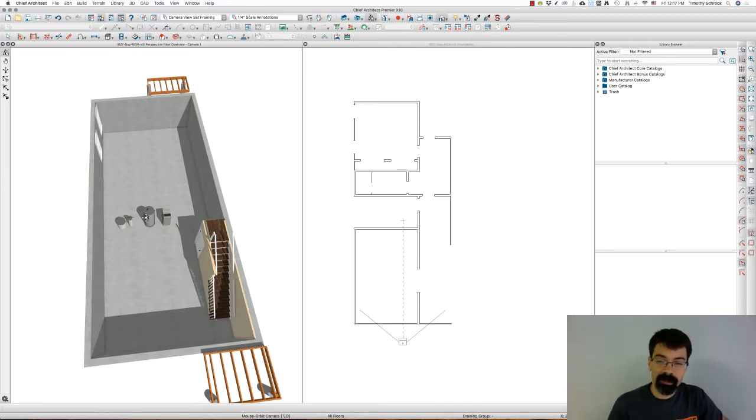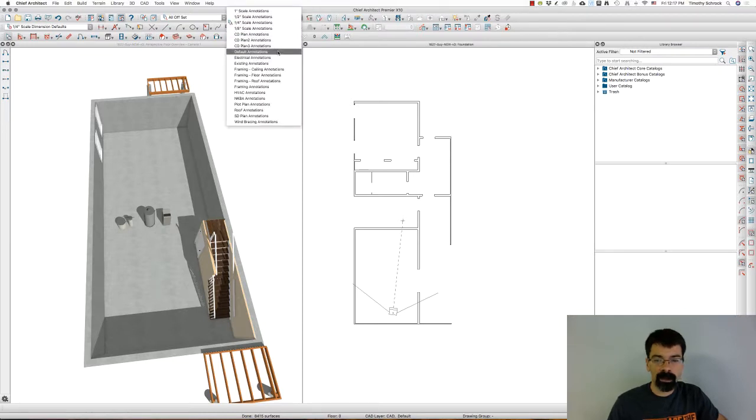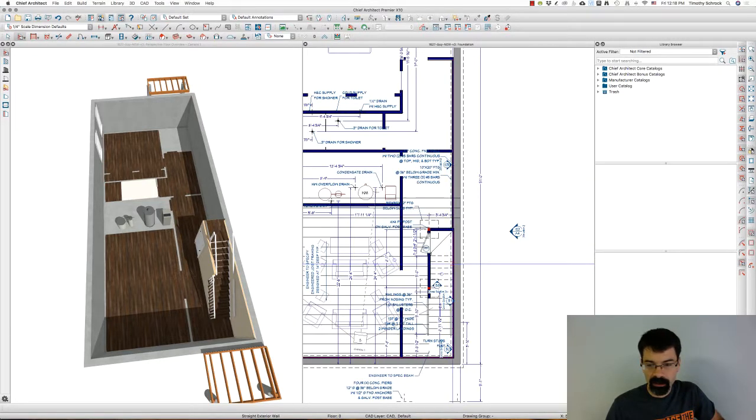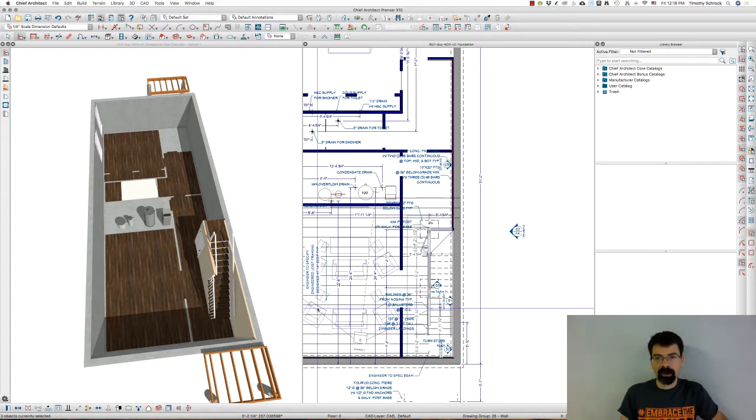The other way you could do that, instead of changing your wall types, is just select, let's go into default here. Instead of building all the framing, you could build all the framing, delete all the framing on this level, the foundation level, and then you could select just the walls that will be built. This wall next to the foundation and these two walls here, and build those framing individually. The quickest way would be to go into the framing dialog box, build all the wall framing, delete the wall framing from the foundation layer, and then select the individual walls that will actually be framed out.